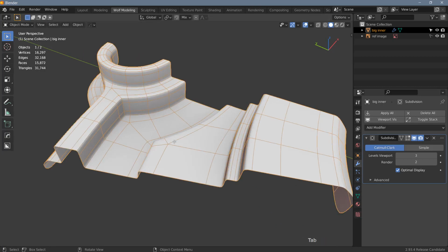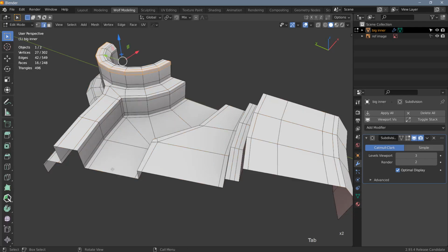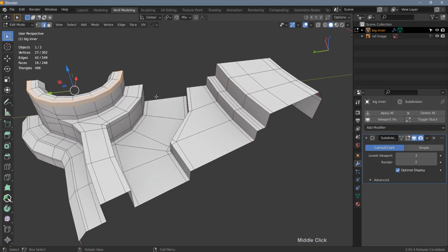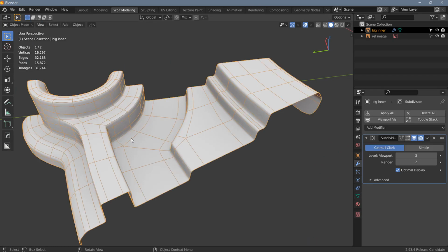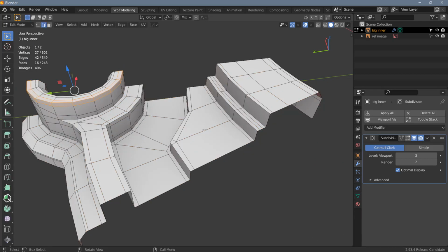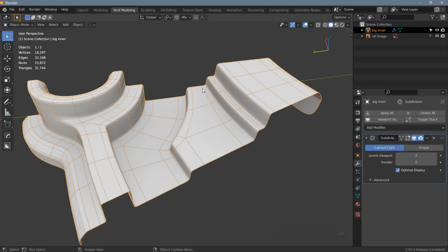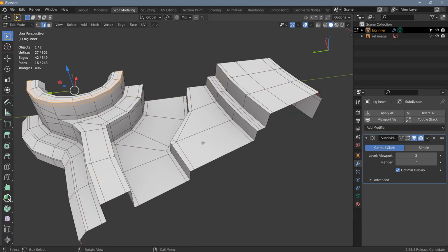If I go to object mode and the object gets subdivided, you can see that the control edges get pulled away quite a bit from their original position. And that's because we don't have any geometry in between here. And down here at the bottom, I don't actually want to add any more geometry. At least the edges get pulled away evenly. But up here it's a different story, because we have polygons that have different widths, and that means if we subdivide the object we get a sharper bevel here and a softer bevel here, and I want to keep this even, so I will add a little more geometry up here.